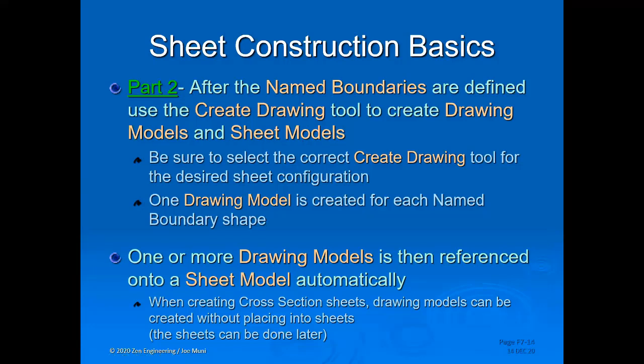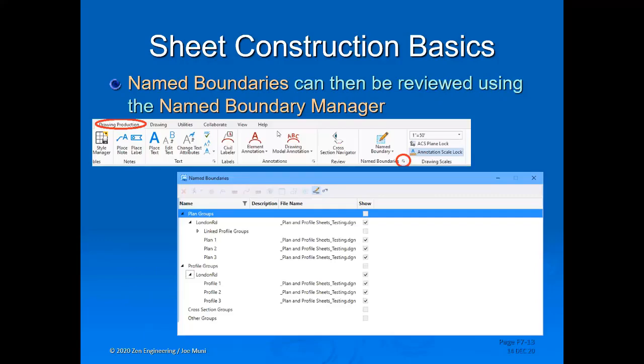Now, the one trick here, and I'll point this out when we do the live demo, you want to make sure you're using the correct tool along the top of this dialog. So if I were to pick any one of these different groups here, all these will kind of ungray out or undither. And there's a lot of different methods for creating sheets, and you want to make sure you pick the right sheet that matches up with the seed that you've picked.